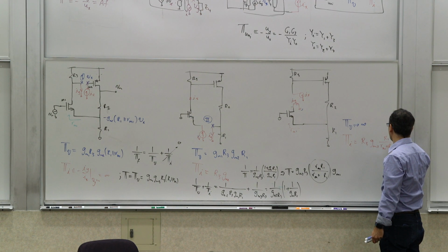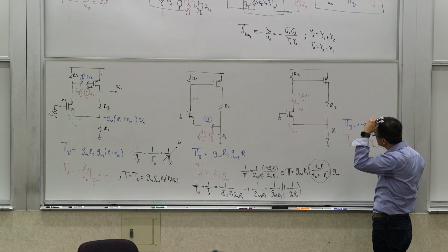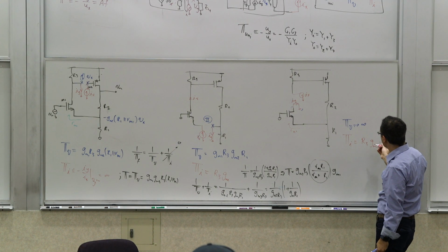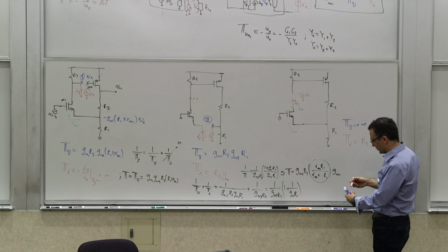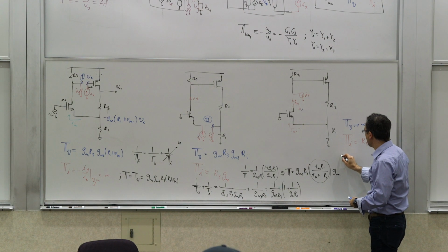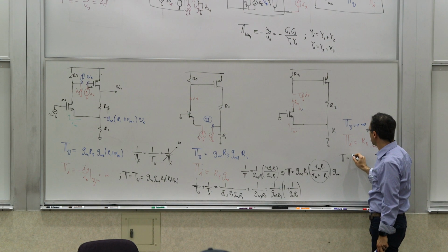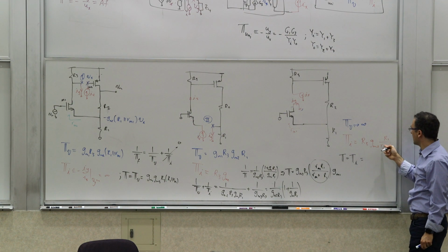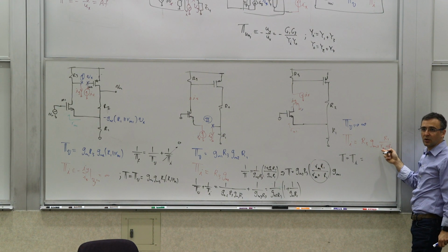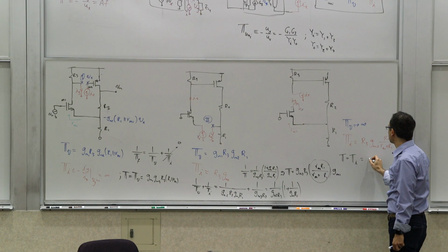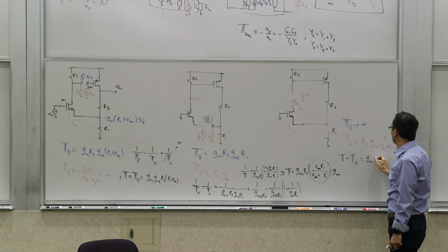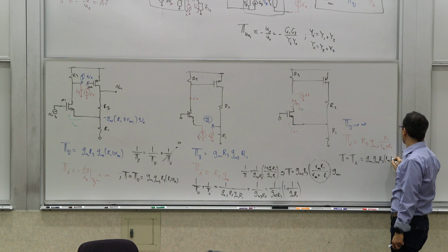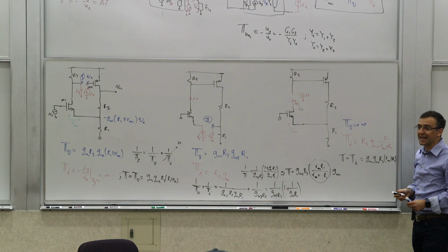So that's the current that goes through there. And again, you can see that the total loop gain is going to be just the current loop gain because this is infinity. And again, you can multiply by GM1 RM1, which gives you the same expression. You can write it as GM1, GM2, R3, RM1 parallel R1, which is the same again.